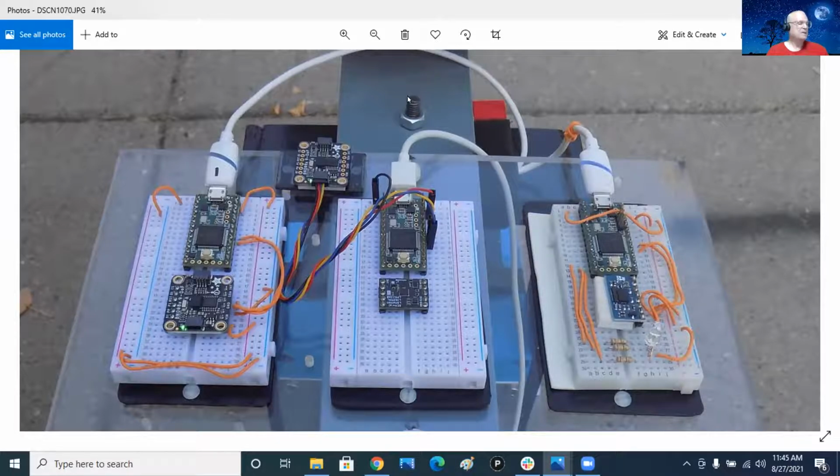So if the steel is screwing up my 2 BNO085 IMUs on the left, well, that's one less thing I'll have to worry about. Because what I find odd is, if I sit in my house in my lazy boy in front of my TV, with my Windows laptop plugged into one of these boards and fire it up, it'll say, yep, it's calibrated, and it looks like it's working quite well. But if I take it outside bolted on the robot, I can't get it to calibrate. It says I'm off by 20 or 30 degrees or something when all is said and done.